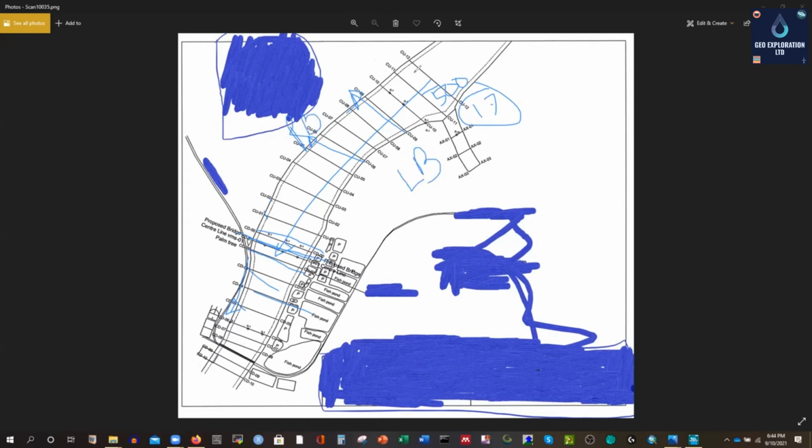So at the upstream cross section here, we need a boundary condition, right? So we'll provide Q, flow rate or discharge, as a boundary condition, and at the very downstream, if it is there, we'll provide the water level, right? So for Q, we'll calculate the 100-year return period of the Q. We have historical data from different observation stations, and then we'll use the Gumbel extreme distribution method to calculate this 100-year return period of flow rate, and same for water level.